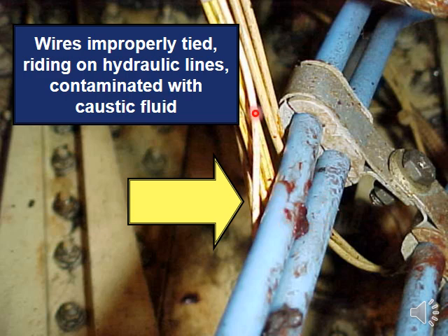And also you might have noticed that these wires aren't bundled tightly together. They're just free flowing about. So the wires need to be bundled, the area needs to be cleaned, and there should not be any contact from the wires to the hydraulic lines.